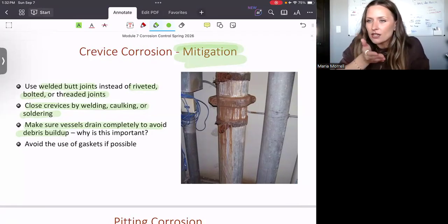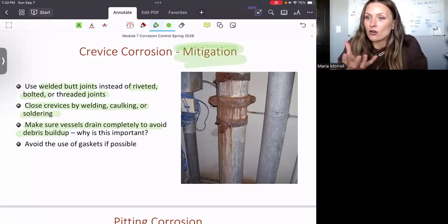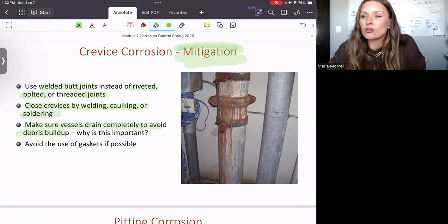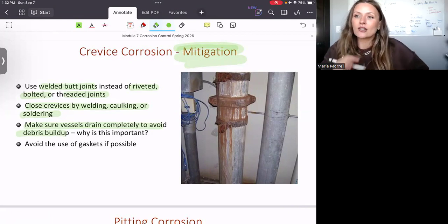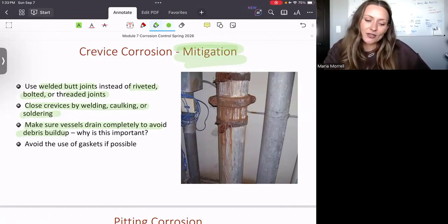There's a specific area in the car where you can see a significant portion of corrosion happening, or it's going to be everywhere where you have a chunk of dirt hanging and you don't do anything about it. That means there is an oxygen concentration galvanic cell that is running day and night until you remove it and let the corrosion happen, right? This is why it is important.